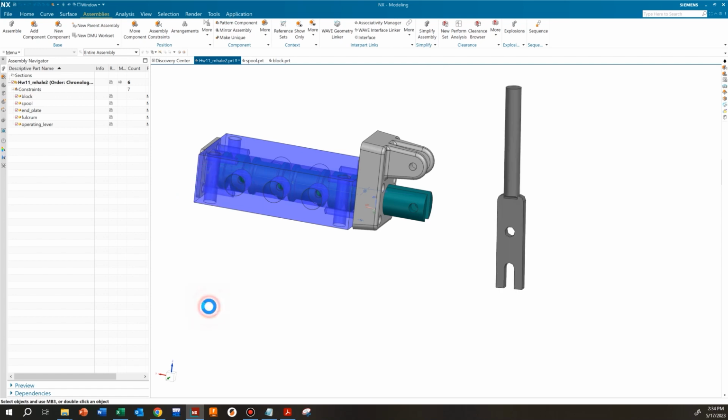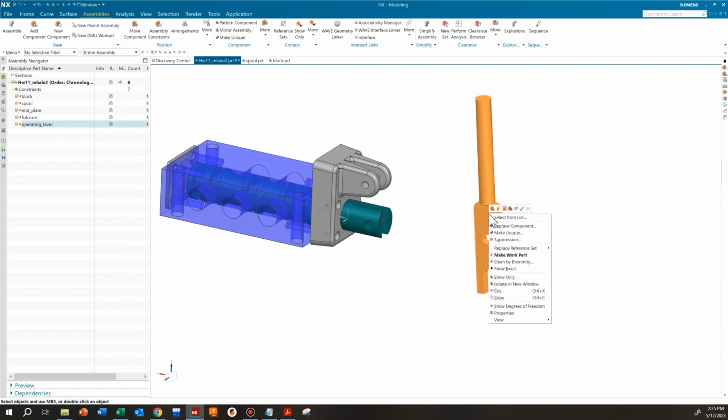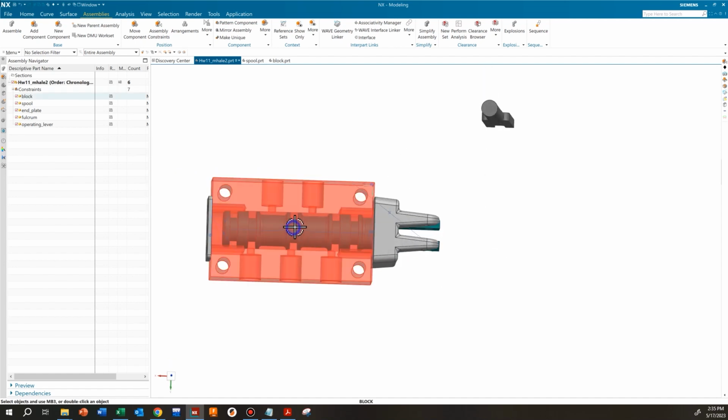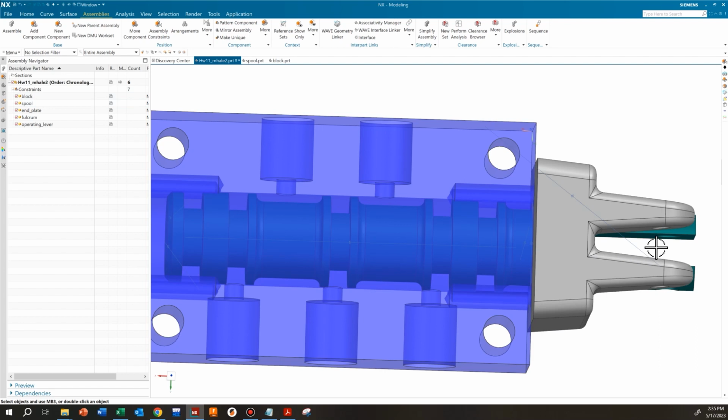And that's good enough. We'll go ahead and show the exact on this. And this is going to rotate around this hole, which is positioned in the fulcrum. And so as you move this lever forward, it pulls this spool out. And as you pull on the lever, it pushes the spool in. That's how we're changing which valve is being selected.